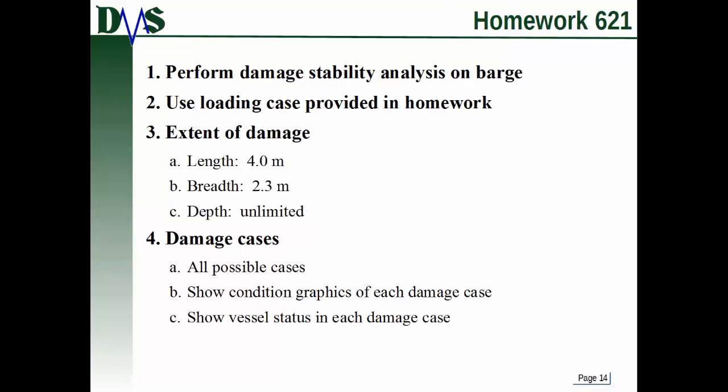Right, but this isn't just about talking. Time to practice this yourself. So, homework number 621, I would like you to perform a damage stability analysis on the barge. The homework has a loading case already provided, and I'm not going to give you any regulations to look up, so I'm just going to tell you the extent of damage. It has a length of 4 meters, a breadth of 2.3 meters, and a depth that is unlimited. So this is a horizontal box, 4 meters long, 2.3 meters wide. So anything that's 2.3 meters in from the side shell gets damaged.